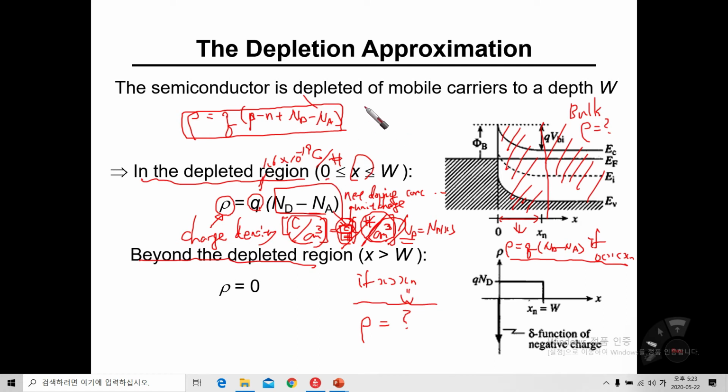In n-type silicon material, n is more dominant than the hole concentration, so you can ignore the p value. And the donors and acceptors would be mixed together in n-type silicon material because basically it is a p-type silicon substrate, and you can inject many donor atoms so that the net doping concentration is defined as Nd minus Na instead of simply Nd only, right?